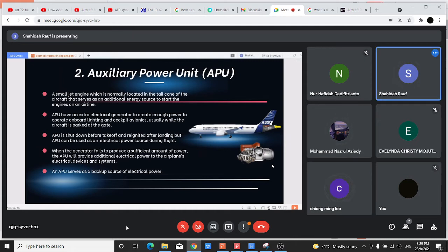Once there is a two-engine failure, there are a lot of checklists the pilots have to do to determine which ones are the priority. If your APU is also not available, that means your RAT system comes in to give you the emergency electrical supply, or your battery gives you basic instruments to land. That means your landing gear must be available. That is a must.